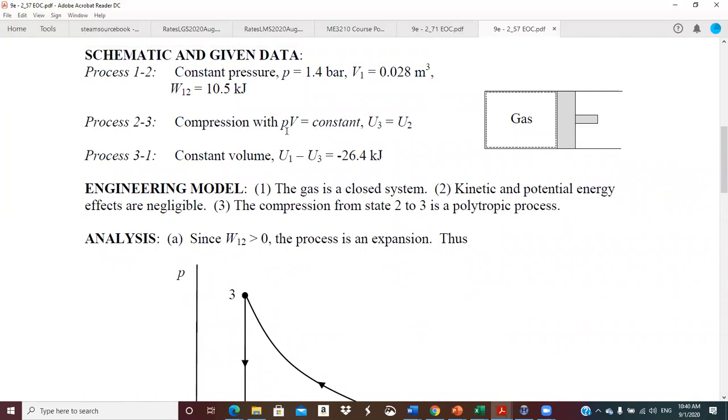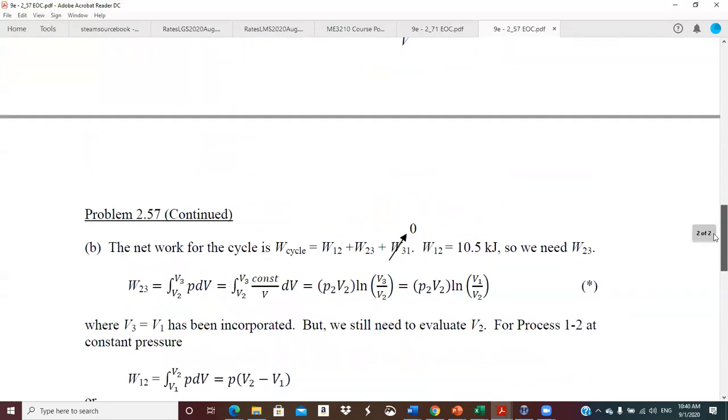So you want to solve for P in terms of volume. And that's what he's done and substituted in. So P is equal to whatever that constant is divided by V, times dV. Well, that constant is P1 V1 or P2 V2, whatever state you know both, that evaluates the constant, because the equation says that pressure times volume at any point is constant.